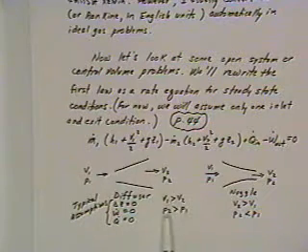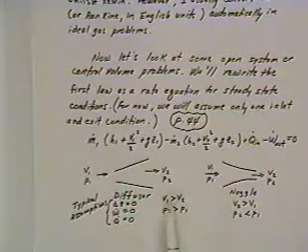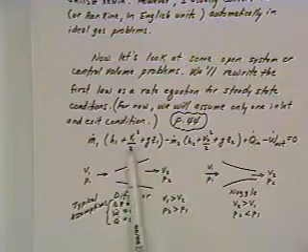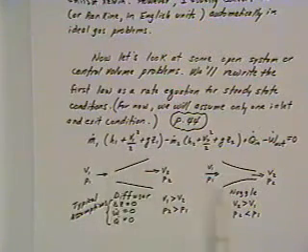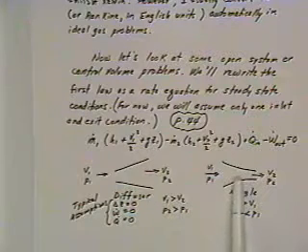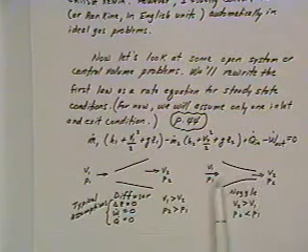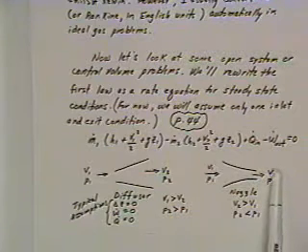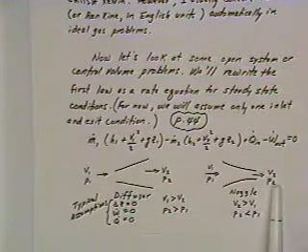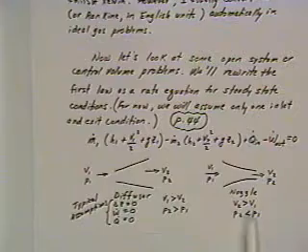So the terms that are generally significant are the kinetic energy terms and the enthalpy terms. For a nozzle, you've got just the opposite case: V2 is greater than V1, you're speeding up the fluid, and the pressure P2 is less than P1.